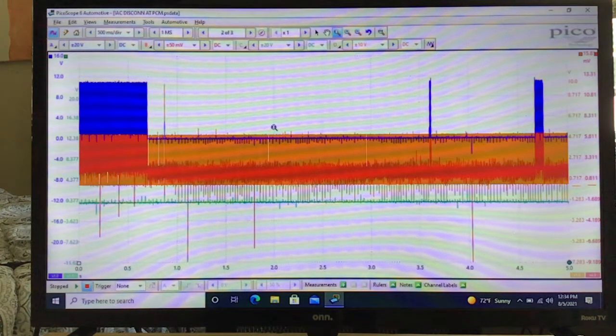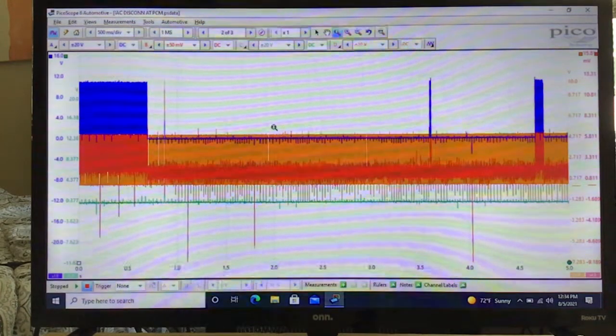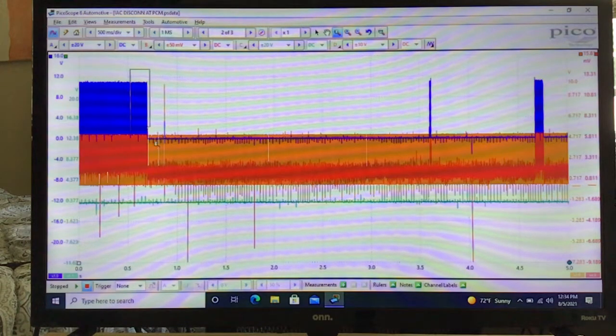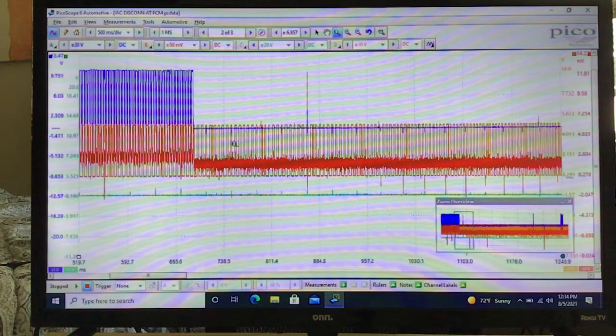As you can see, the voltage goes low, and I'll key in on that. Let's take a look, and we can see right here it became disconnected, and our engine's still spinning. Our IAC is unable to make any duty cycle.